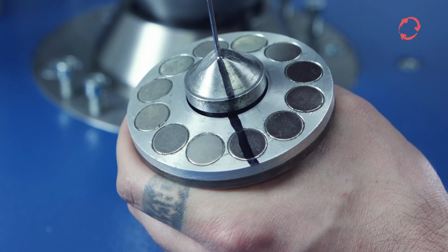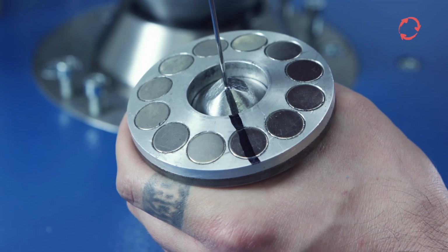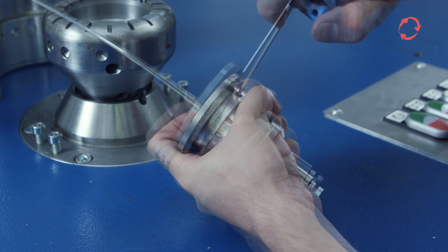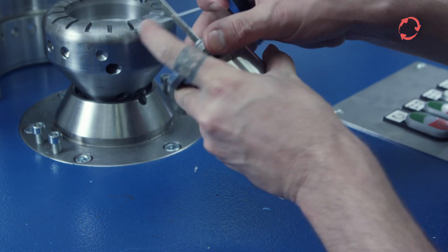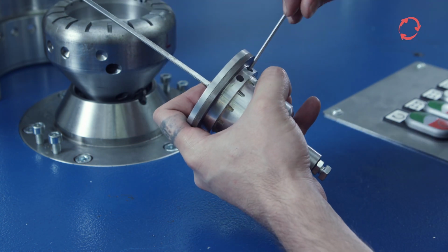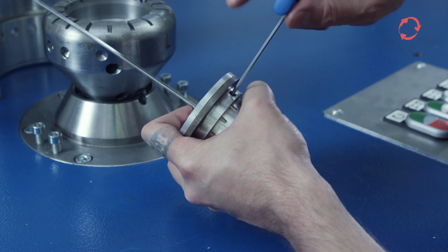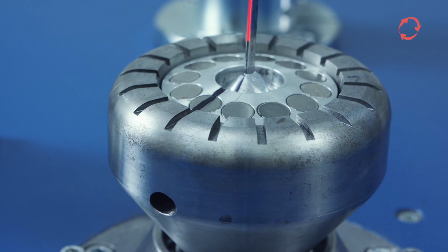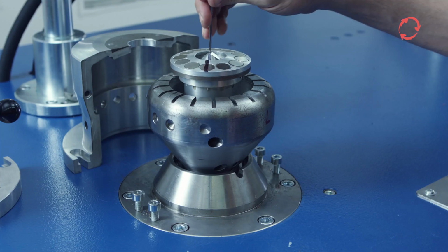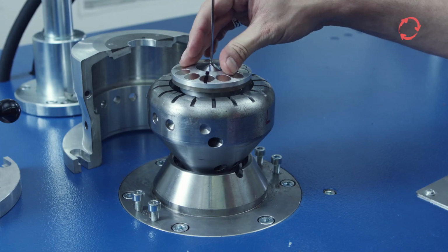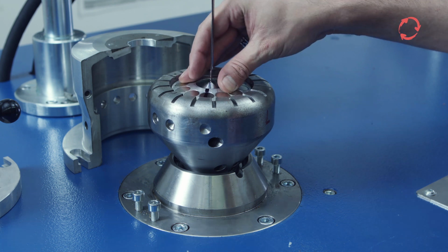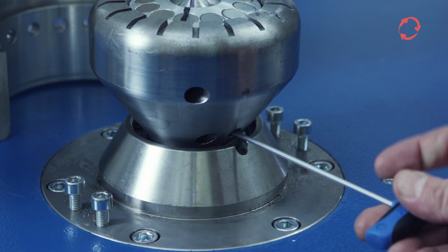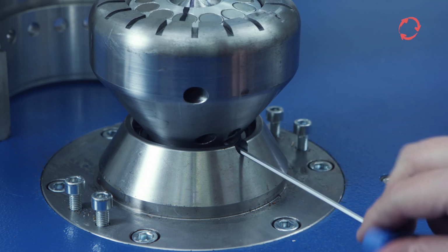To insert the new mandrel, follow the reverse order of this process. Then screw both clamping screws down again, and pay attention that the mandrel is positioned perfectly in the intake. When inserting into the intake, the narrow side of the mandrel must again face the marking. Then insert the mandrel intake, with the newly mounted mandrel, back into the winding head, and tighten the screws on the winding head firmly again.